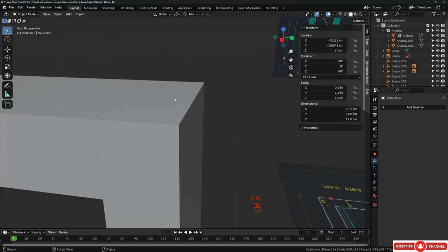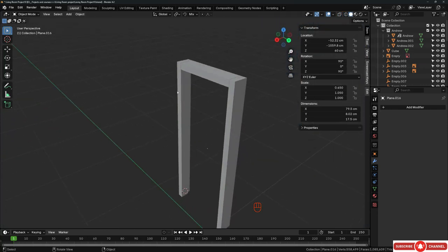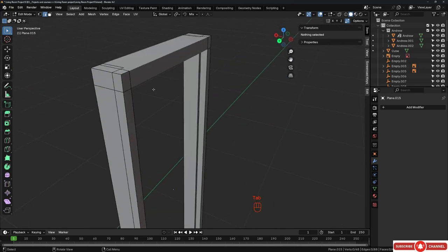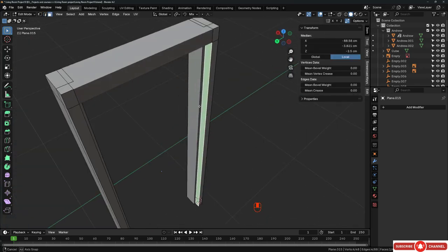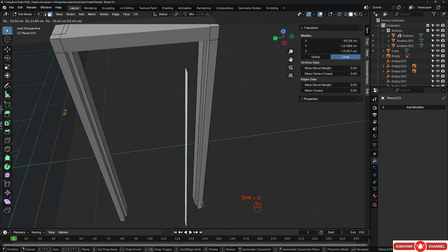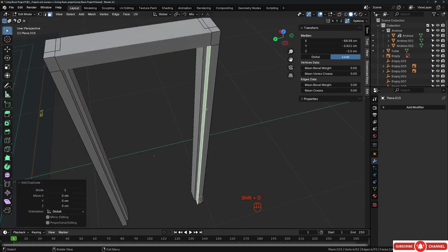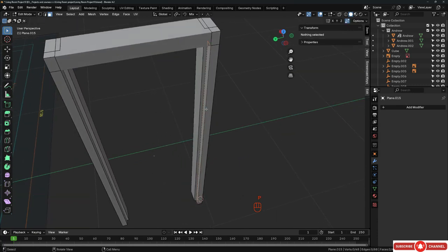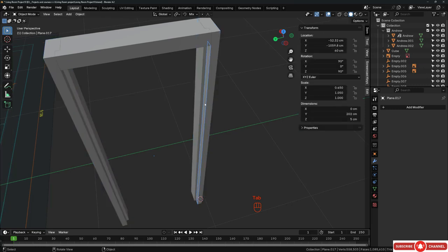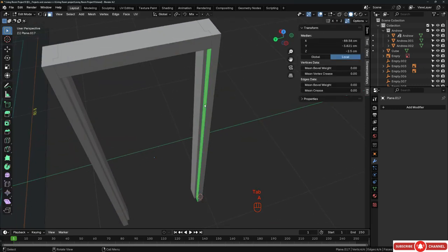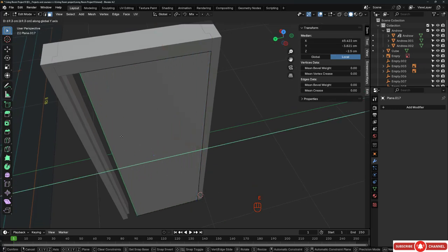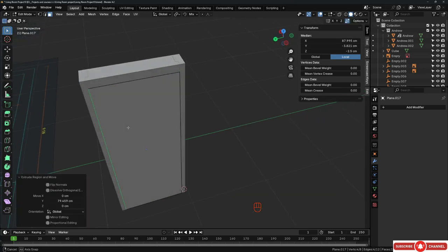All right, after that, we can focus on the door itself. I will grab one piece here, and I guess we can select this face and use it. Hit Shift D to take a copy like that, right click to leave it in the same place, and then hit P and then S to separate this out. And now I will grab this new piece, hit Tab, hit A, select this face, hit E to extrude this, and snap it right here.